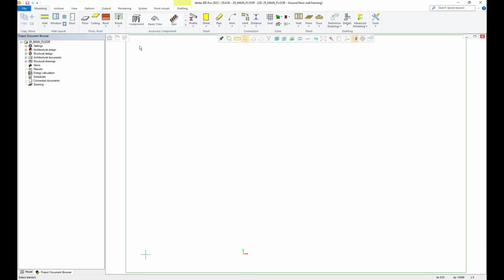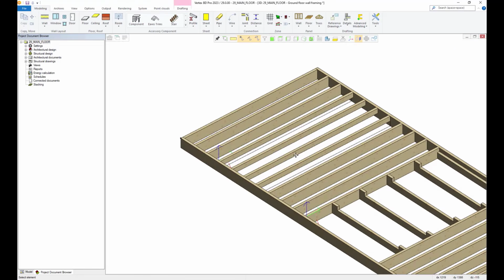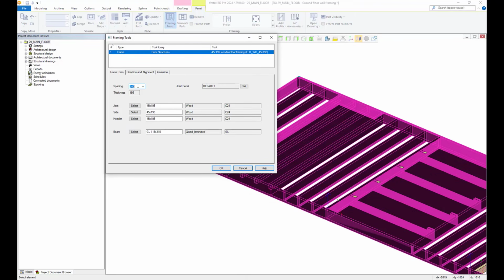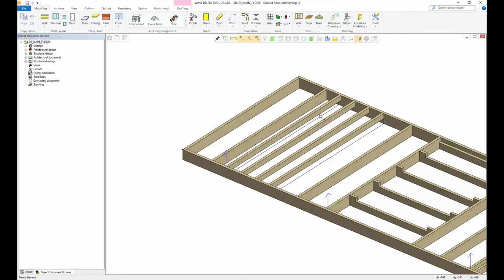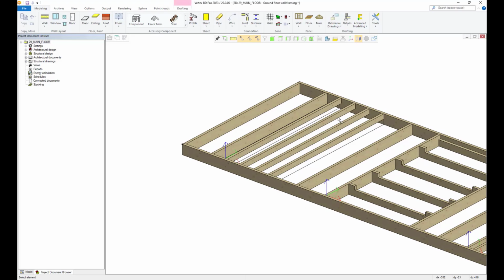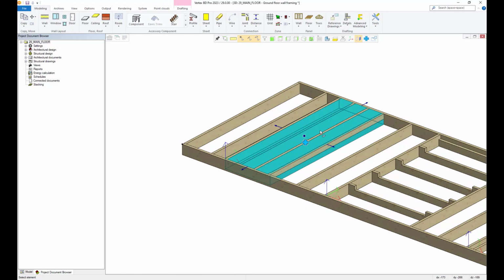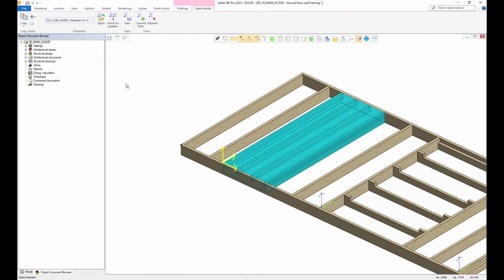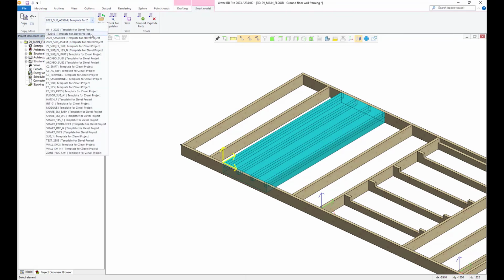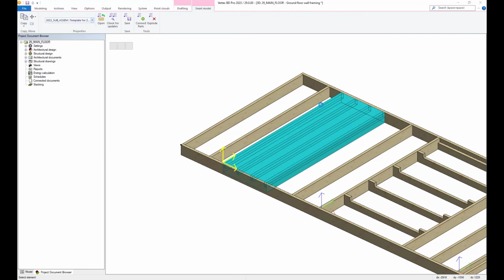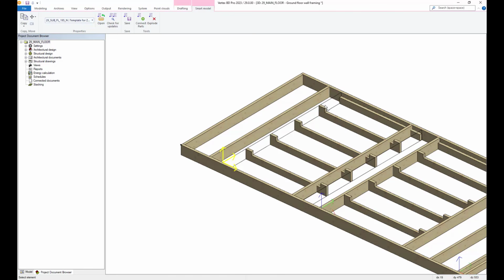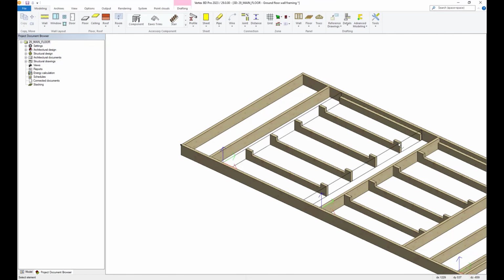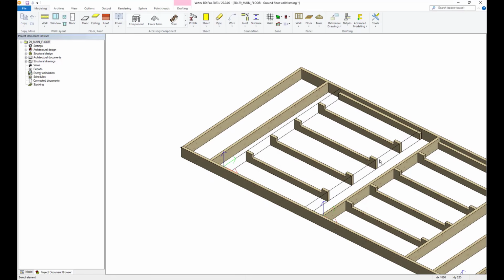Here we can see the new Smart Model we created. As you can see, if we change the framing spacing, our Smart Model ignores these global changes due to us having previously made sure our Smart Model is non-updatable during its creation. Let's select the Smart Model subassembly we created and change it to another one. We simply select our existing smart model, and then from within the drop-down, we select another as required. The software then replaces our previous subassembly with our new selection and fully updates everything within the flooring panel. Now, as you can see, there are two types of the same subassemblies in our floor panel.